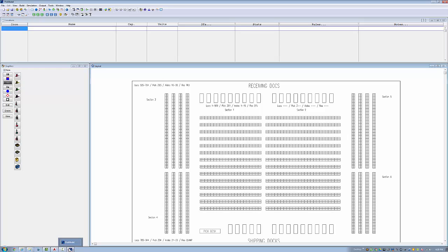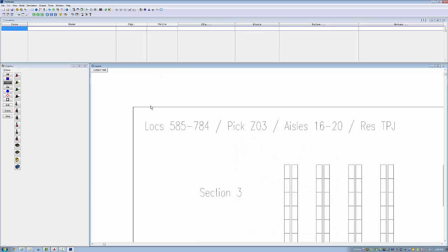Alright, so what I need to do now is I have to tell AutoCAD what the locations are in my ProModel model by pixel. So I'm going to come up here to View, and I'm going to come down here to Show Layout Coordinates, and now I have a little XY coordinate system, and I'm going to zoom in, maybe a little more.